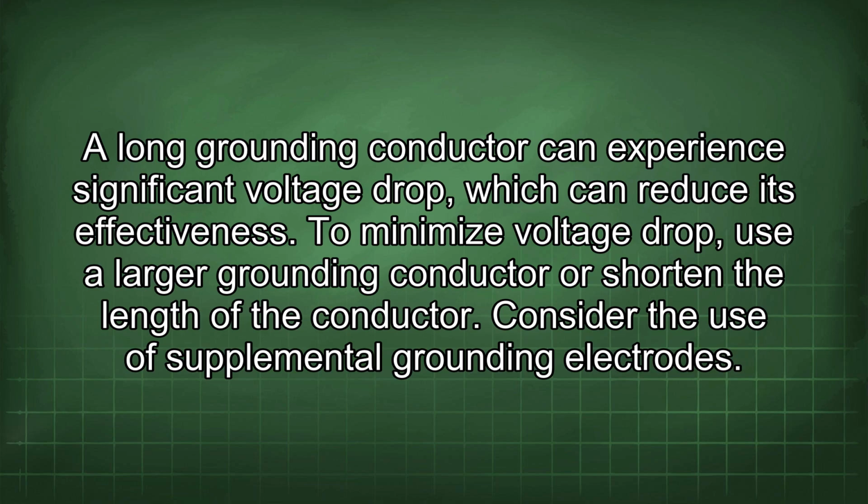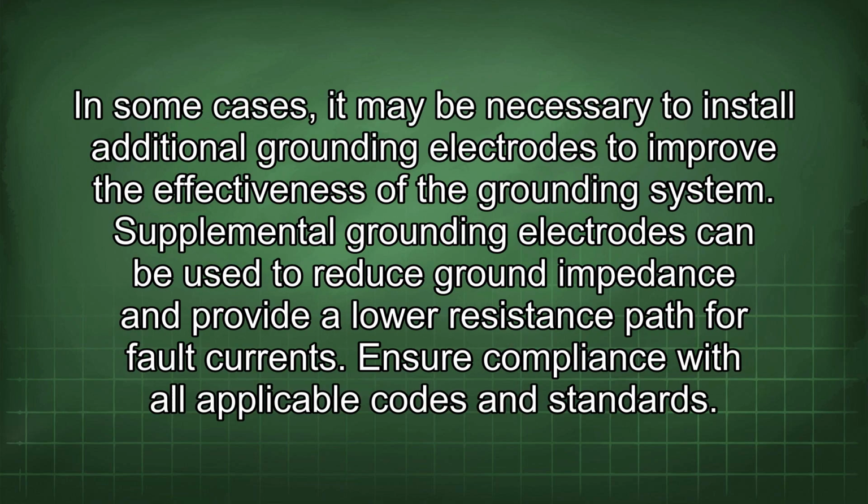Consider the use of supplemental grounding electrodes. In some cases, it may be necessary to install additional grounding electrodes to improve the effectiveness of the grounding system. Supplemental grounding electrodes can be used to reduce ground impedance and provide a lower resistance path for fault currents.